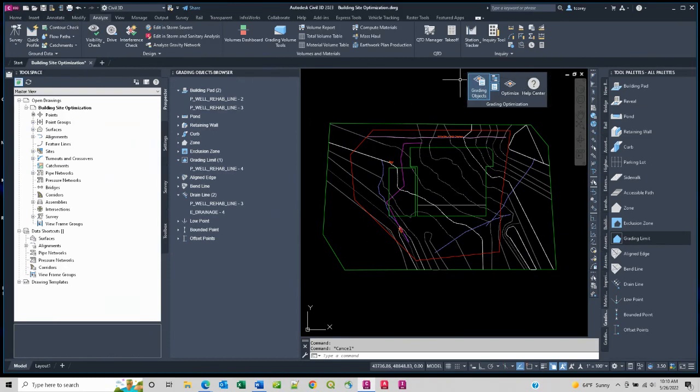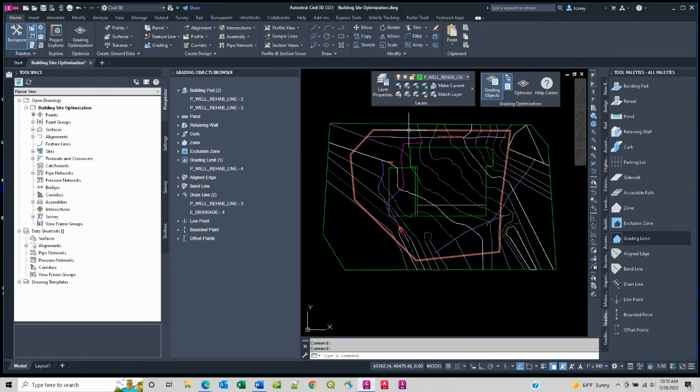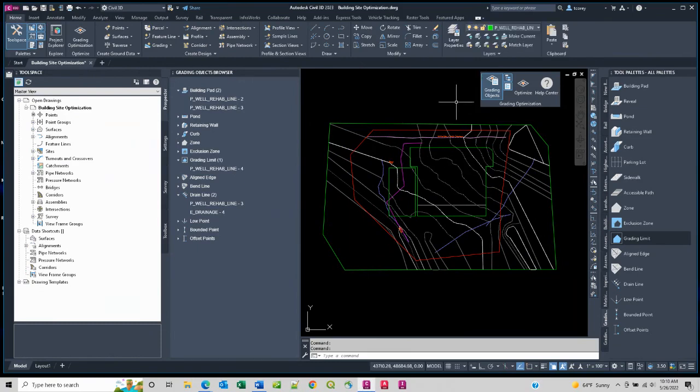Now, when you're done, if you want to put that back, you point here and you see this top button, that's Return Panels to Ribbon. Okay, and you can do that. That's a little trick that you can do with really any ribbon panel that you have out there. Maybe you use layers a whole lot, where you could drag that out if you wanted. Okay, I'll put that back. So set it all up in here with all your properties, and then go to Optimize.